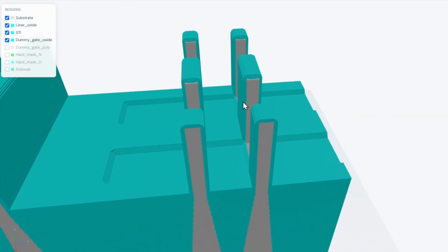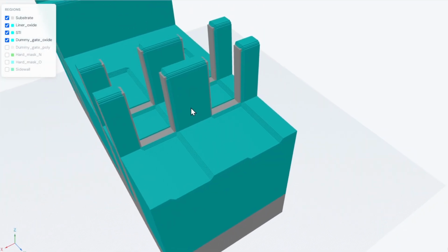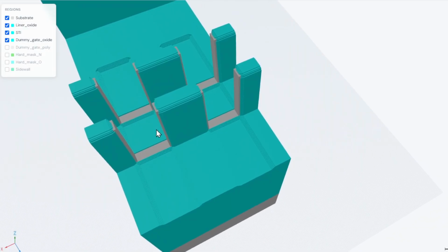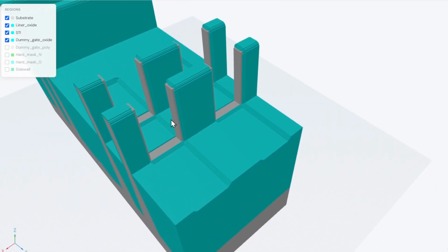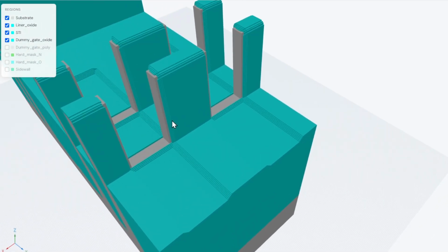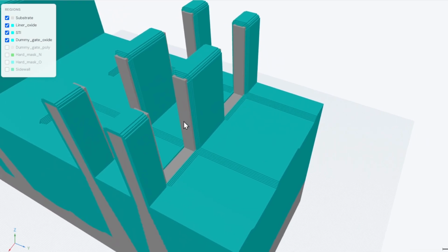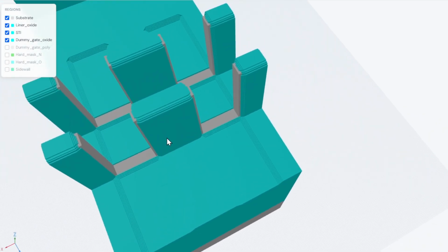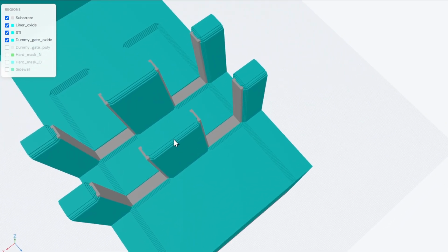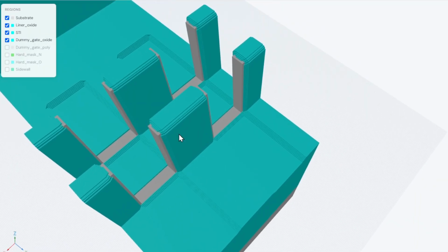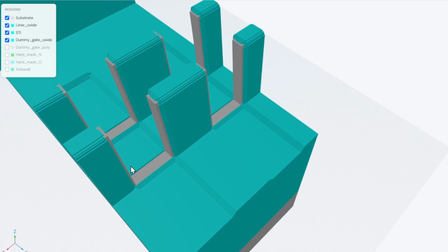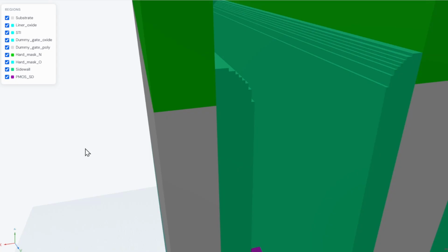That is typically called the kinetic lattice Monte Carlo method. Monte Carlo is the methodology that uses random numbers, and kinetic lattice means that we have a lattice structure of silicon, and there we place silicon or silicon germanium atoms on it.